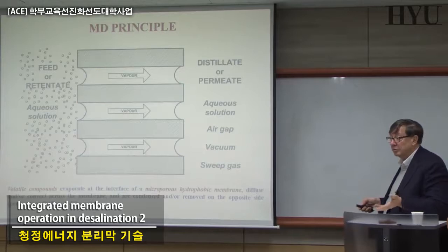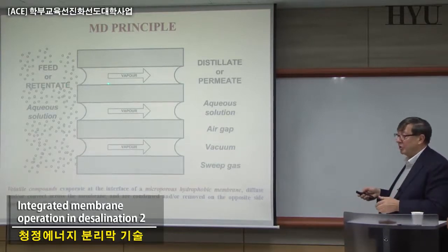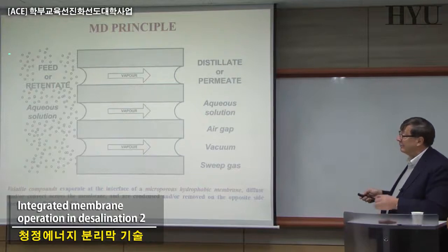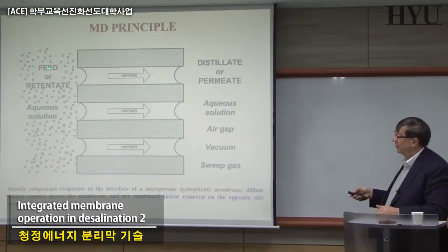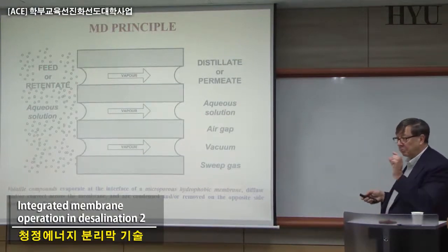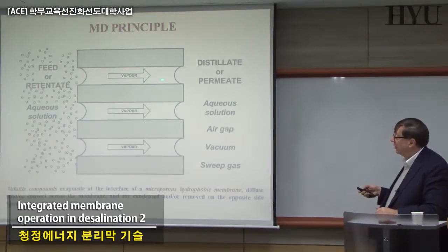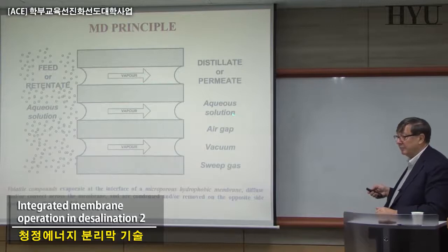One is that at a certain temperature you will have evaporation at the interface between the liquid phase and the gas phase. Some molecules are going into the vapor phase. If you apply delta T between this area, 30 degrees here and 25 here, very small, you don't need a very high delta T, these molecules will migrate from one side to the other in vapor phase, not liquid.